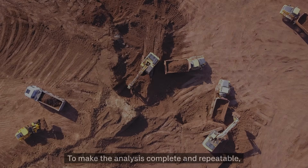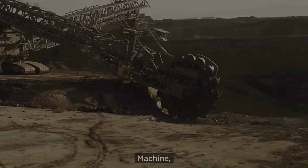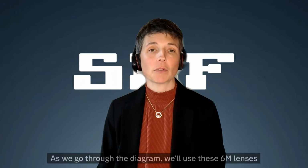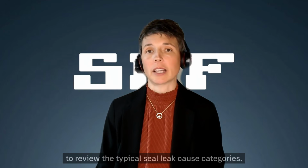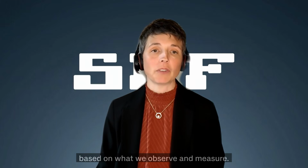To make the analysis complete and repeatable, we apply the standard 6M headings: man, machine, material, method, measurement, and Mother Nature (environment). As we go through the diagram, we'll use these 6M lenses to review the typical seal leak cause categories, and we'll eliminate candidates step by step, based on what we observe and measure.